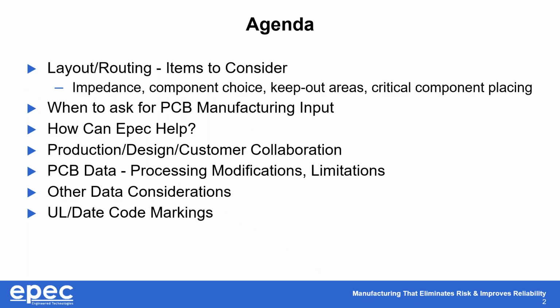So our agenda today: layout and routing. This is the step before where I typically get involved, after you've come up with your concept and you've got your layout. When to ask for PCB manufacturing input, how Epec can help, production design, customer collaboration, PCB data processing and lamination limitations, other data considerations, UL, date code, and markings.